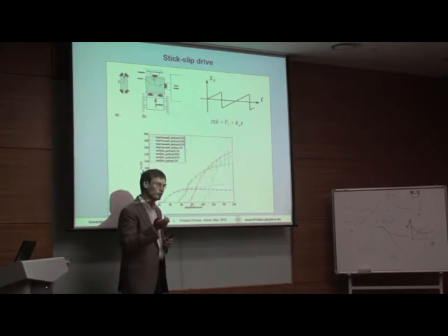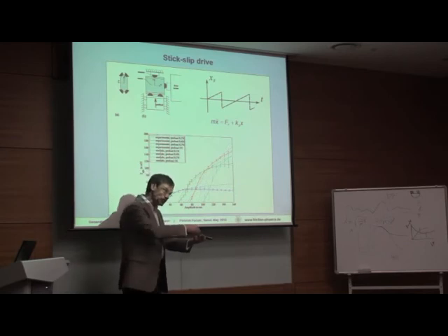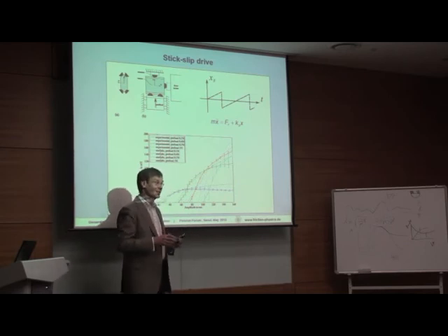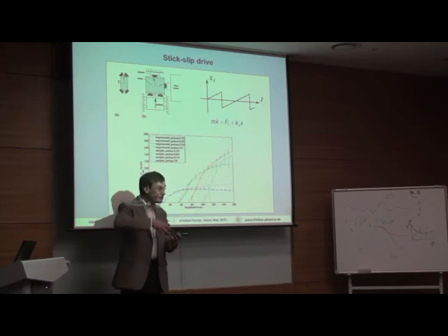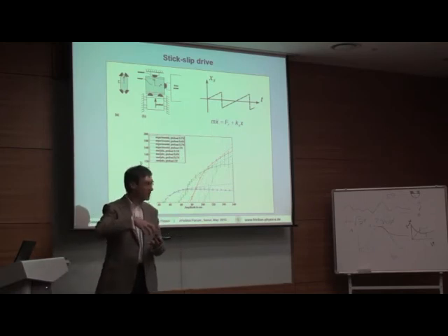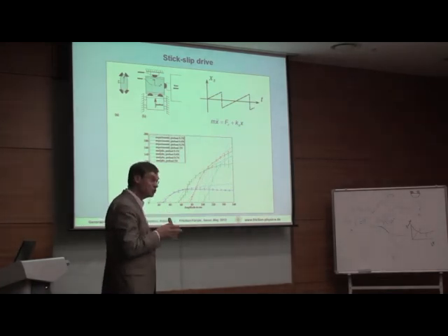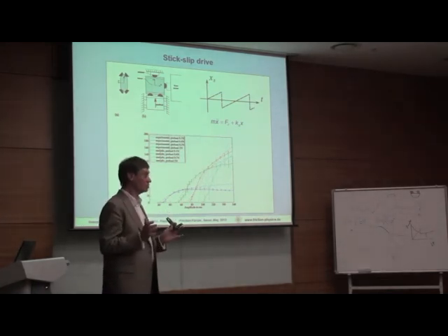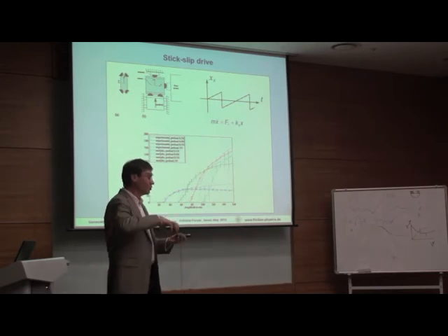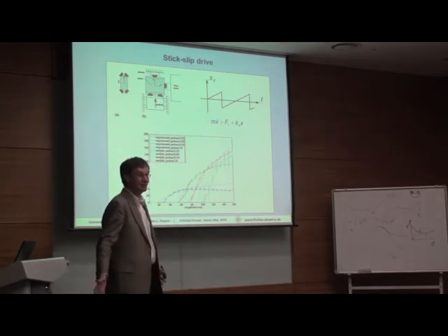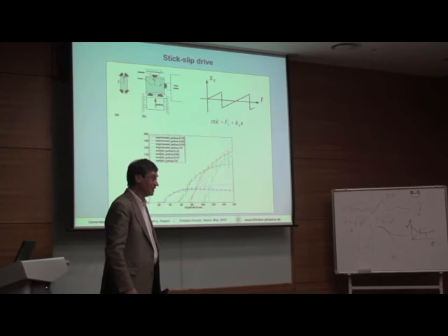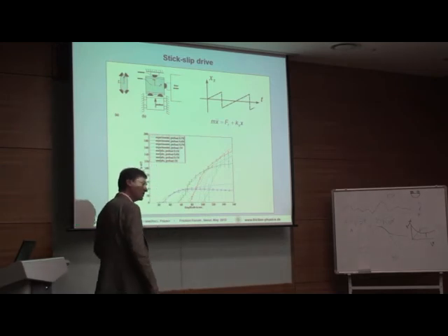It is an elastic model of sapphire, of steel, the radius, the frictional coefficient measured, no fitting parameters. So this complete frictional law, including pre-sliding, is just pure contact mechanics, which has to be done. If you do not consider the contact mechanics, then you have to invent some frictional laws.